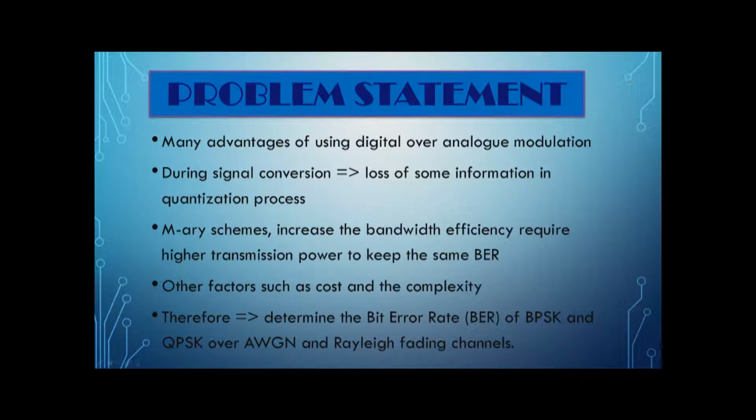In the M-ary schemes, increasing the bandwidth efficiency may require higher power transmission to keep the same bit error rate. Other factors such as the cost and the complexity of the receiver in wireless networks are what engineers will be concerned about. So here, we will determine the bit error rate performance of the PSK modulation schemes of BPSK and QPSK over the AWGN and the Rayleigh fading channels to figure out which modulation scheme is better.